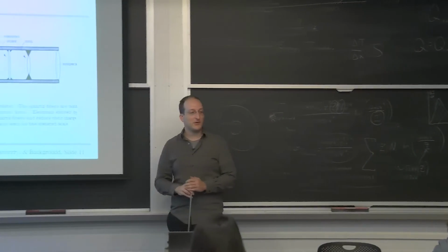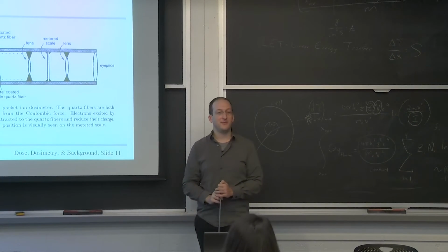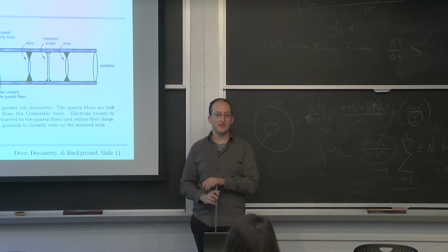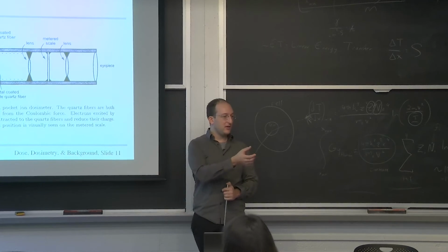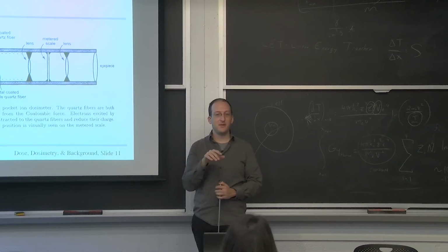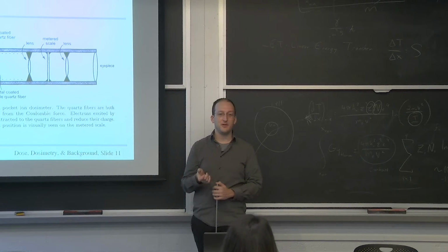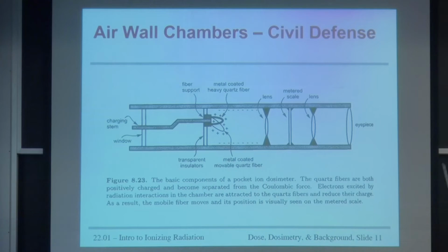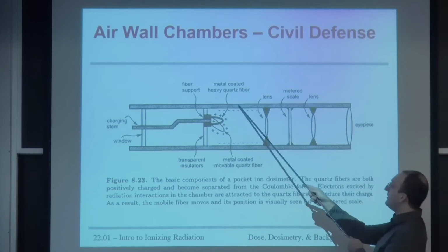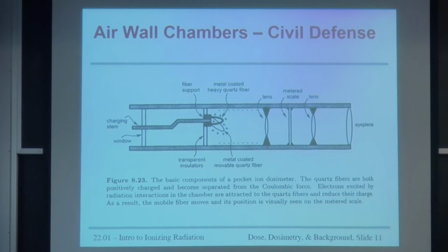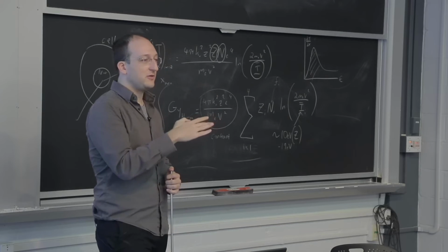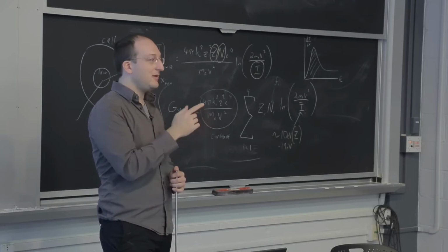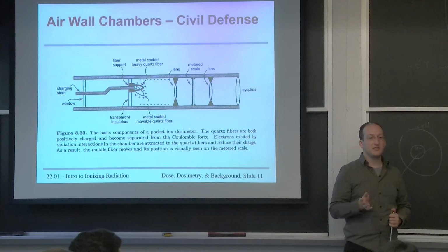I want to tell you guys how it works. It's a battery. That's it. If you open that thing up, there's a couple of big D cells in there and a voltage divider. And you just turn the knob, which sounds complicated. All you're doing is turning a potentiometer to decide at what voltage this wire end inside of the tube will be. And that voltage deflects the wire a little bit by just Coulombic attraction or repulsion, bends it, and gives you the dose. And it stays there.